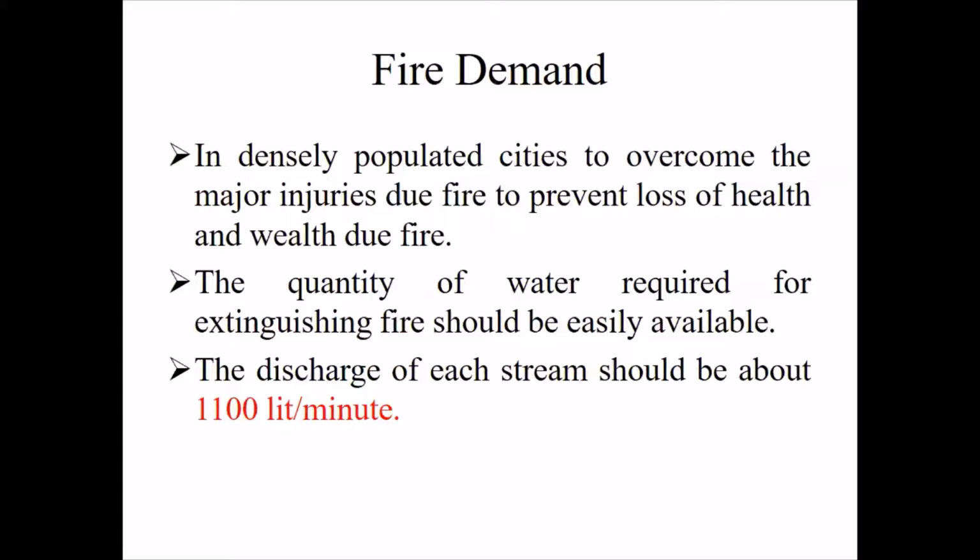Hence, the required amount of water for firefighting should always be stored in an underground reservoir at a specified place, and fire hydrants should be established in the main pipeline at intervals of about 100 to 150 meters, so the quantity of water required for extinguishing fire is easily available. The discharge of each stream should be about 1100 liters per minute.